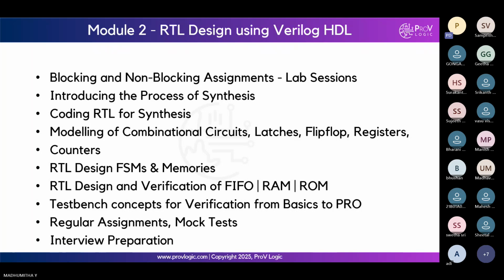For example, if you are going to use a multiplexer in your IC, in RTL you will be using an if-else statement. If you are using a flip-flop in your IC, you will be using keywords like posedge, negedge. Like this, you will be able to model your combinational and sequential circuits using the behavioral structures of your RTL. What I gave is just an example.